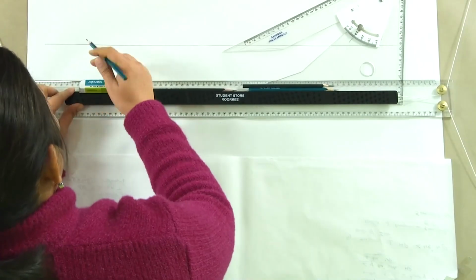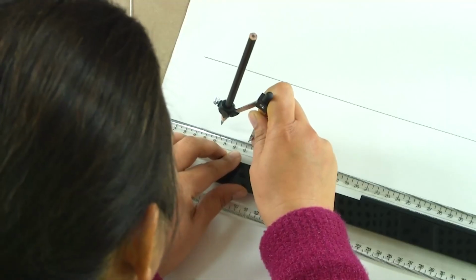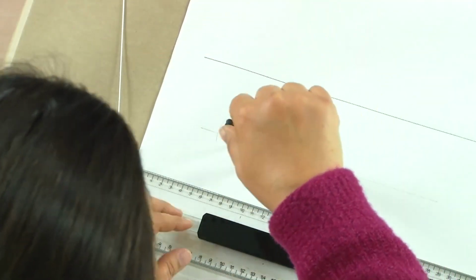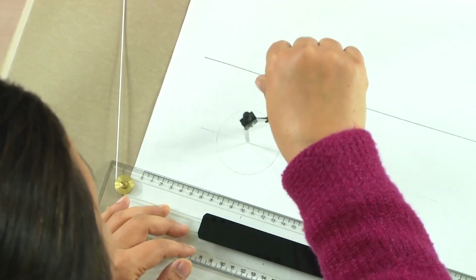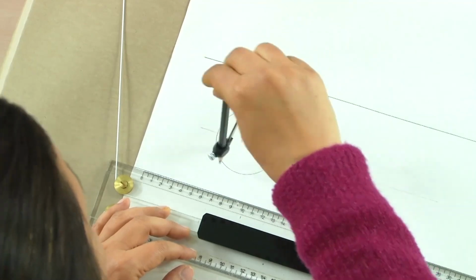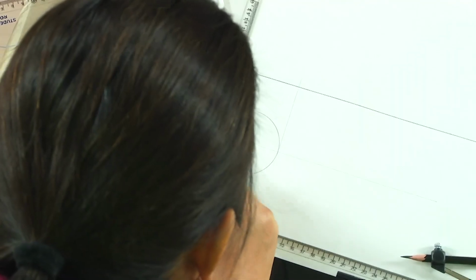So here again one of the points is in HP, so let's assume that one of the points is going to be stationed in HP. So we have a circle. We will draw a circle of say radius 3 centimeters, and to begin with we will assume that this circle is parallel to HP and it makes a certain angle with VP. So this is the starting of this, to draw the circle and take its projection onto the VP.